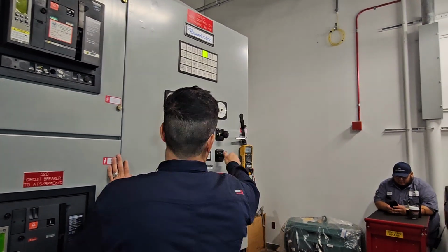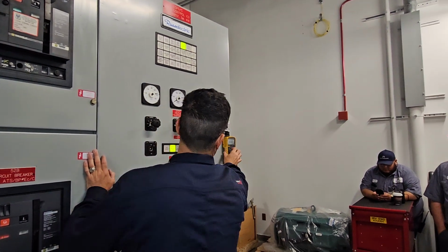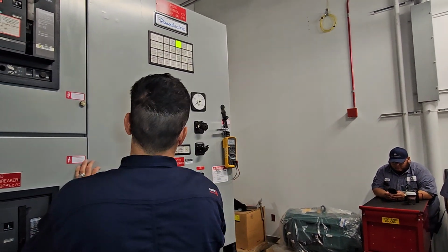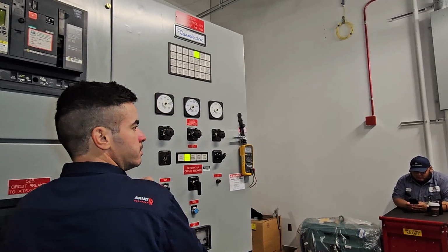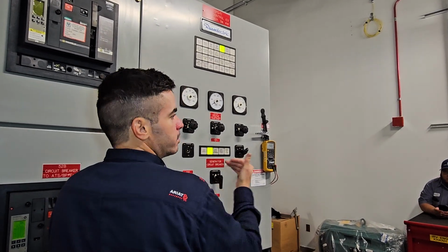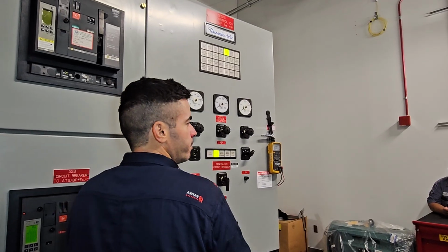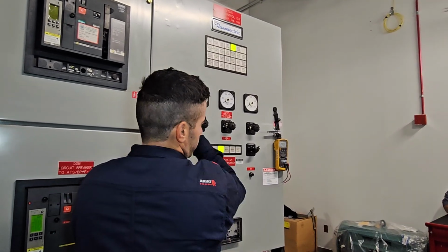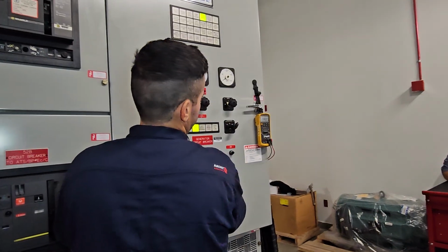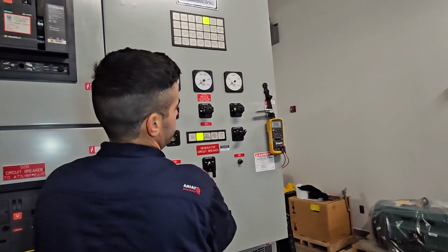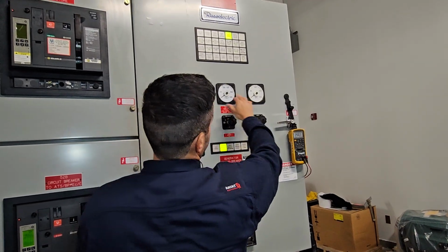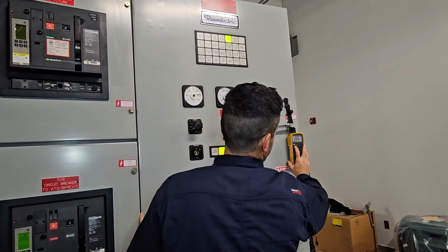And then for the voltage, I can check at the generator, because sometimes they disable that function. When the generator guy comes here, they also check this, so they don't want that to be played with. Yeah, so I'll check afterward to see if they disabled that remote voltage adjustment. It's possible. But we are in acceptable parameters because we're at 480 and pretty close to 60 hertz.